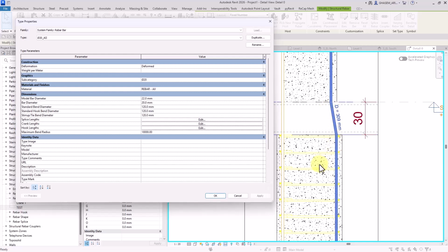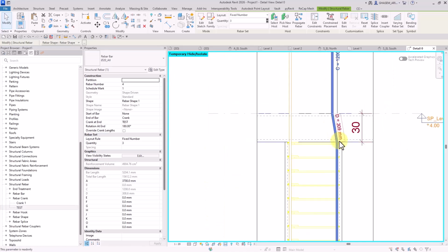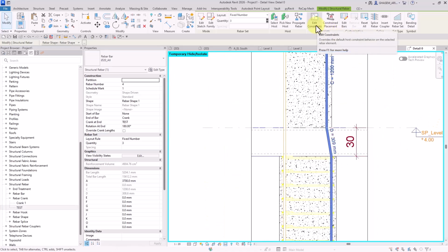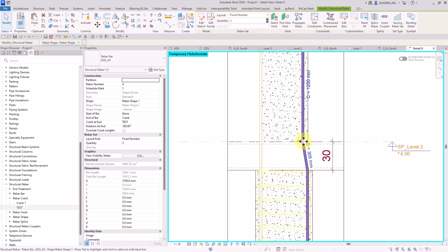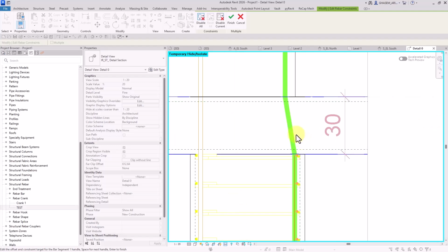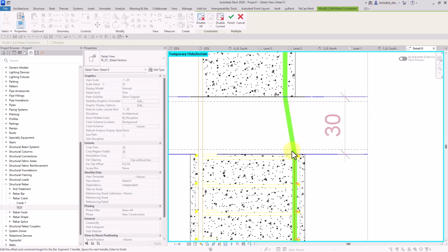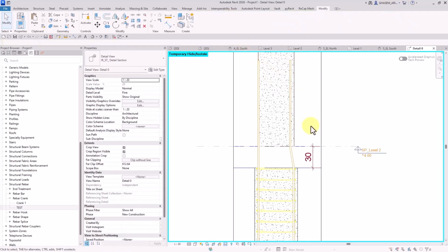Now guys, regarding the placements and attachments in cranks, we actually need to work with 3 constraints. We actually have edit constraints, as you can see. There's one constraint in the top, a middle one, and also a bottom one. So I'm going to hit edit constraint. Okay, if it was set on either sides, we could have just selected this, set these on 0, and we could have done the same for this part. And for the top part, based on this part, I'm going to leave it on 1200 actually. Yeah, finish. We can always change these guys.